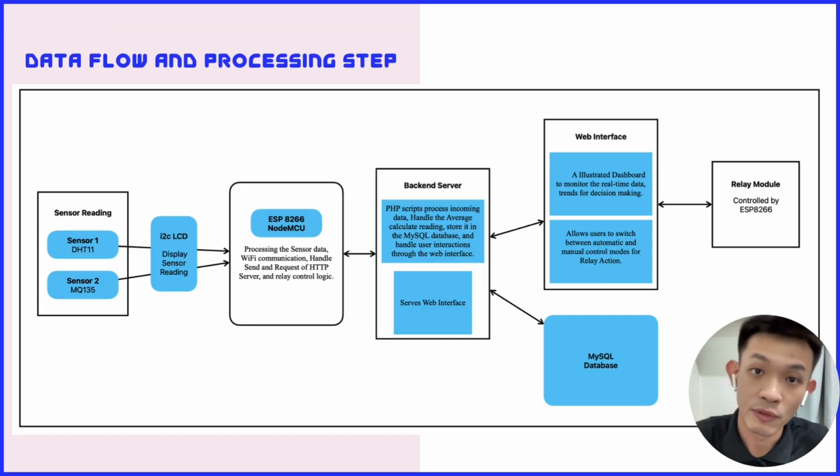Continue with the data flow and processing steps. The system will begin with the initialization of the ESP8266 when it's powered on. The microcontroller establishes a Wi-Fi connection and sets up an HTTP server to manage the incoming requests.